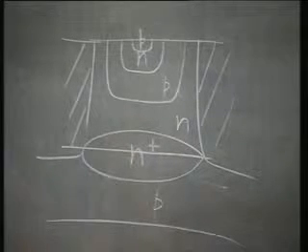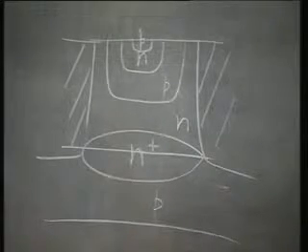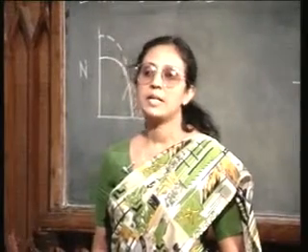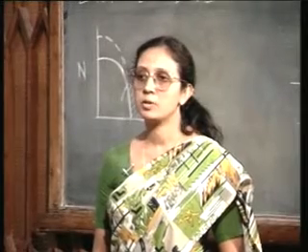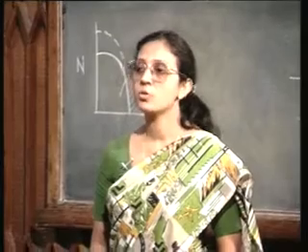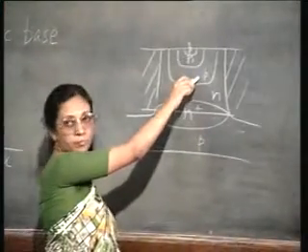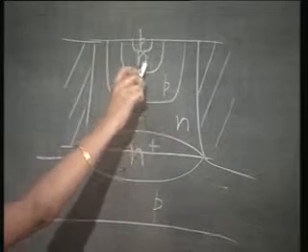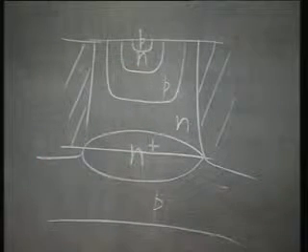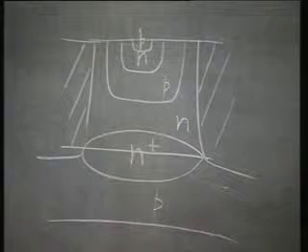This is easy to say, but very difficult to achieve. You see, realizing an NPN transistor by double diffusion process itself is quite tricky, because you are going to use 2 subsequent diffusions, one after another. One for the base of the NPN transistor, the other for the emitter of the NPN transistor. Now, the process we are talking about is a 3 diffusion process.